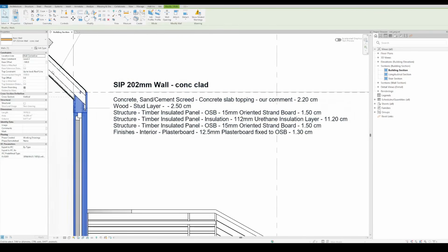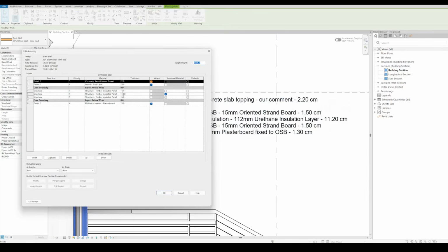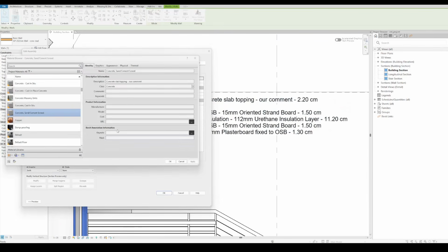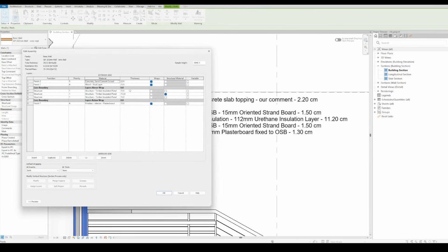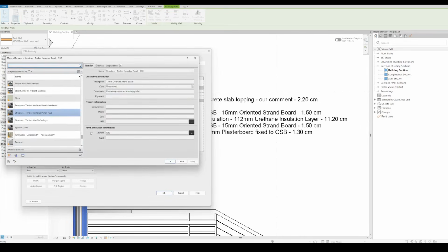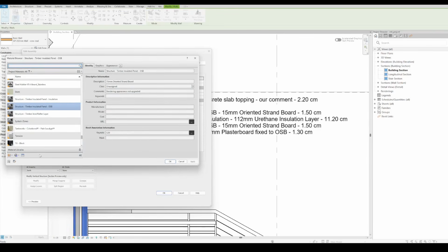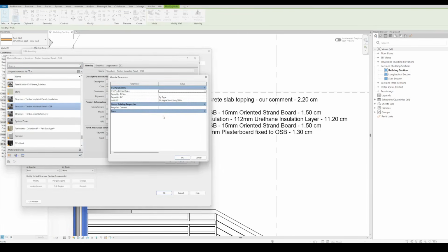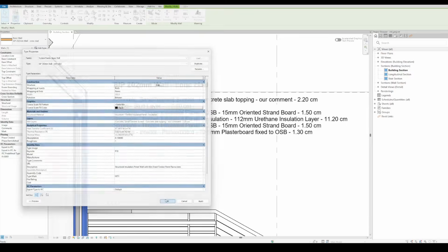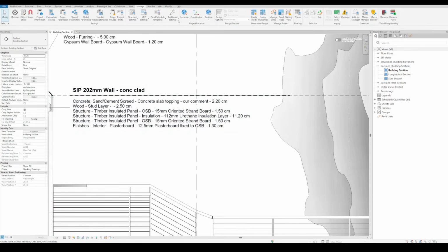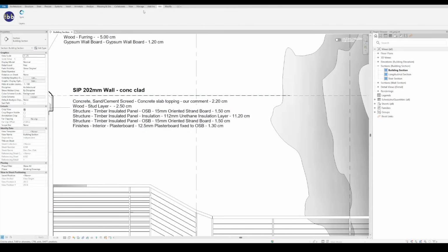Let's edit our wall and edit our material, our custom parameter. Let's add value 1 like this. Okay. And maybe also here, let's add value 2. Okay. This is of course still not visible because we have to update the template.